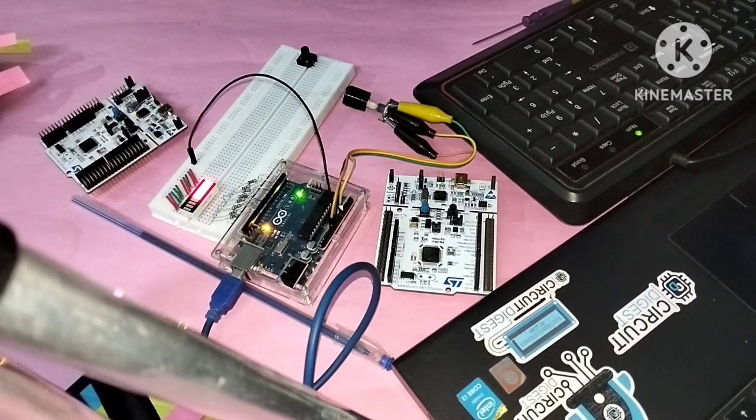The range of LED, I mean to say that I have used 10 LEDs, and whenever we rotate the potentiometer, the LEDs will be on and off as per the rotation, because we are using an analog signal. For example, we have 10 bit ADC in our Arduino, that means 2 to the power 10, that will be 1024, and we are setting the range of 0 to 1023. And wherever we are rotating the potentiometer, we will have the LEDs on and off like this.